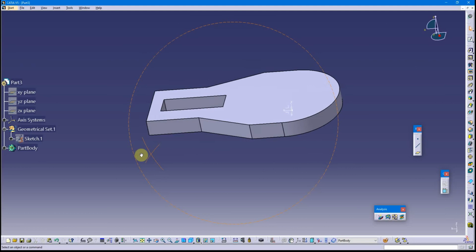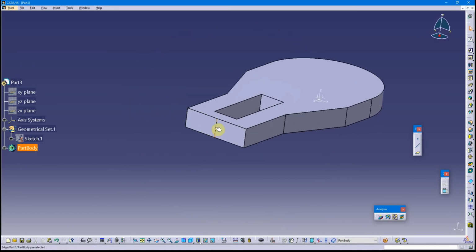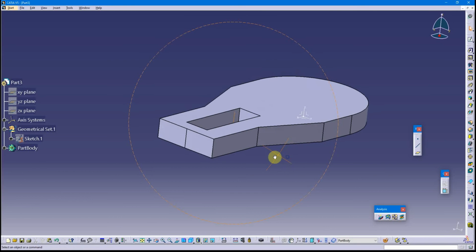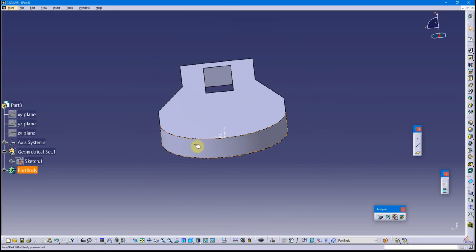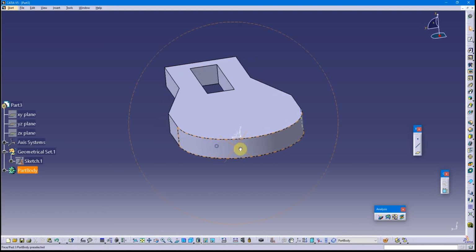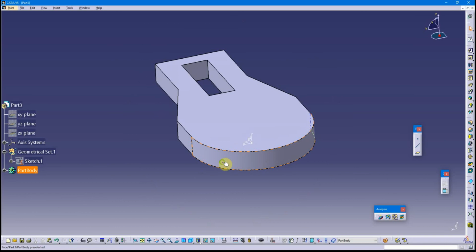Now, see the little topological edge, and that just means the CAD topology. This is a face and this is a face, as opposed to everything being one face. It's not a big deal. It just depends on best practices. Now, by me creating the full arc, I don't have a topological edge here, but it would have been there if I hadn't replaced those arcs. But I think hopefully that's helpful for you.